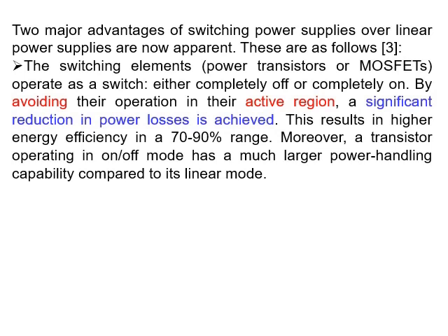Now, as a conclusion, we can say the advantage of the switch mode DC power supply is that the switch is working as a switch, in the saturation region and cutoff region, not in the active region. Loss is almost zero, because in the cutoff region the voltage is high but the current is almost zero, and the opposite happens in the saturation region: the current is high, the voltage is small. At the end both of them lead to low power, and this will reduce the power losses, and the efficiency will improve to be from 70 to 90 percent, compared with 30 to 60 percent in the linear mode power supply.